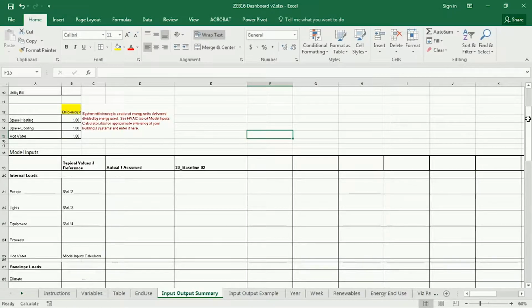So starting out here, I'd like you to begin with the baseline building that has in it whatever optimized mixed mode operation you found. And this should reflect how the building's actually operated. Actually, if it doesn't have mixed mode operation, then don't include it. But if it does have ventilation, natural ventilation, or economizer mode in the actual building, then that is going to better approximate how the building actually functions, and I'd like you to use that now as a new baseline.